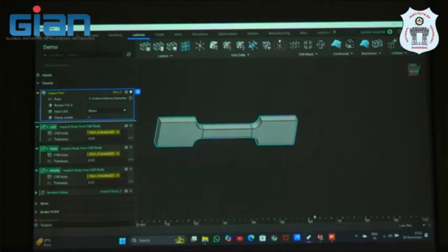We can see this. If you didn't define the design and non-design space, it will remove material everywhere. Design and non-design space means that it will remove material in the specific design space only. Then this will avoid the non-design space holes and bolted joints. Same thing is there for the lattice also. One example is there, the plate. I will show you, where you will get to know.